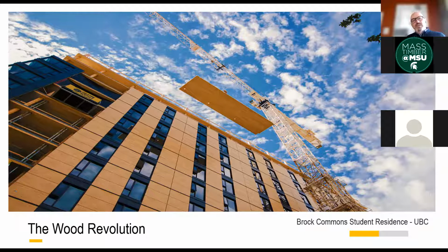What's also very interesting about this building is the use of the prefabricated envelope panels that you see here. These are panels that are made in the factory. They come with the panel structure, the cladding, and the windows pre-installed. And as the structure of the building goes up a few floors, the panels immediately follow, and they're flown into place, and they're quickly fastened to the outside of the building. So this particular building that stands at 18 stories was rendered completely weathertight in only 9.5 weeks.